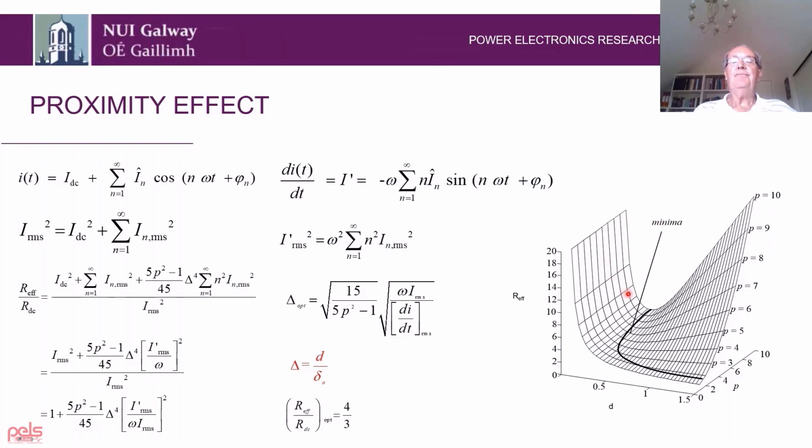Now, in order to generate this graph, we have to take the Fourier series, take each of the harmonics, calculate the effect due to Dowell's formula, add up all the components in our power loss, and then plot this. Quite a cumbersome task, and as I mentioned already, we would have to do it for every single waveform. If the duty cycle changes, we have to regenerate it, and so on and so forth. But thankfully, there's a different way to do it and an easier way to do it. And if you just bear with me, a small little bit of mathematics here.